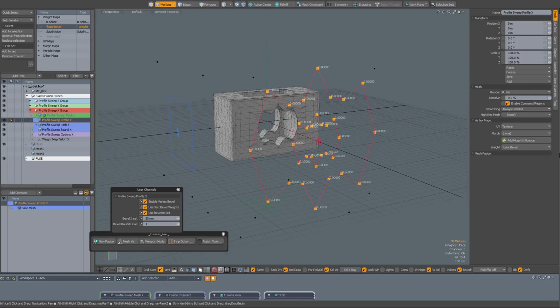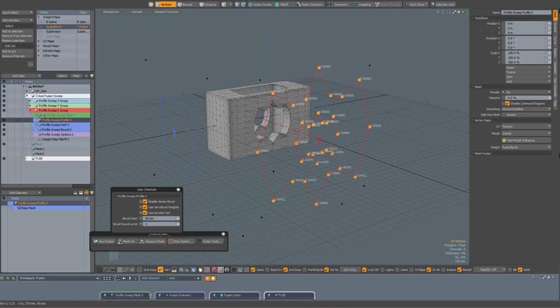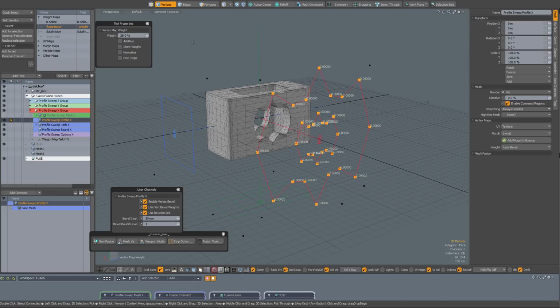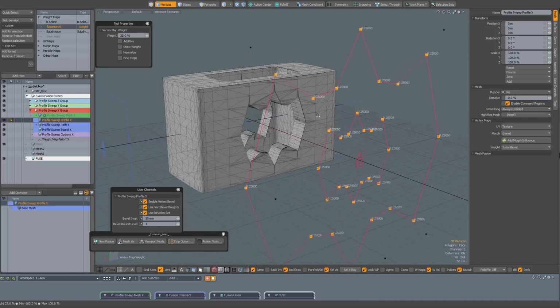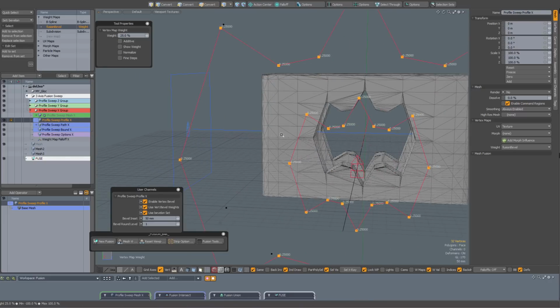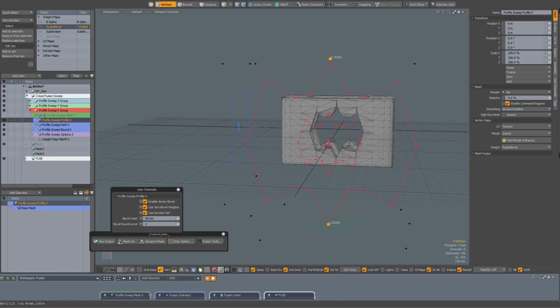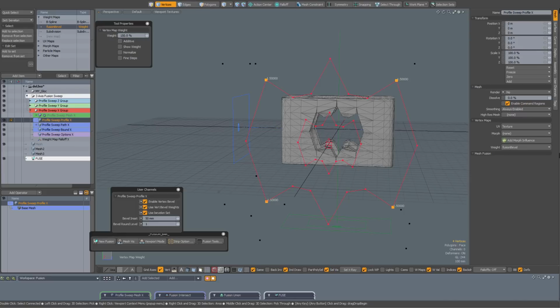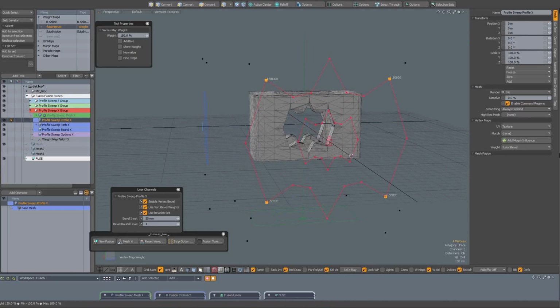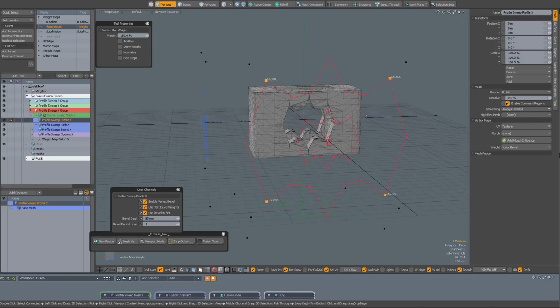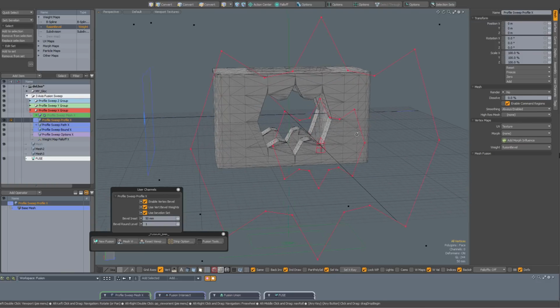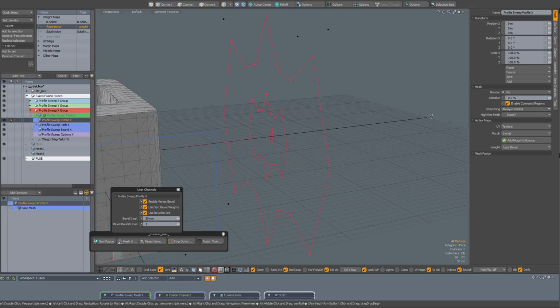and also my weights are 0 right now, so Shift W, and for instance 25% with my weight map fusion bevel selected, click in the viewport and everything gets updated. So if I adjust the weights, for instance, of maybe these outer ones, Shift W to about 150%, click in the viewport. Yeah, that won't make much of a difference because everything is being cut out because of the intersect of the other axis, but these inner ones, they will...